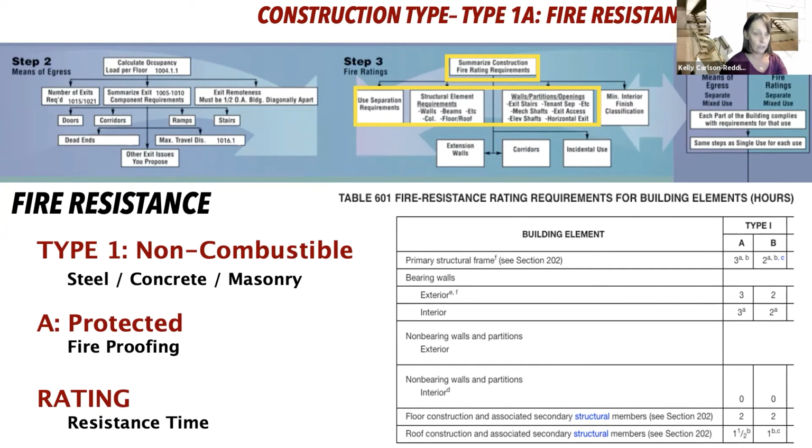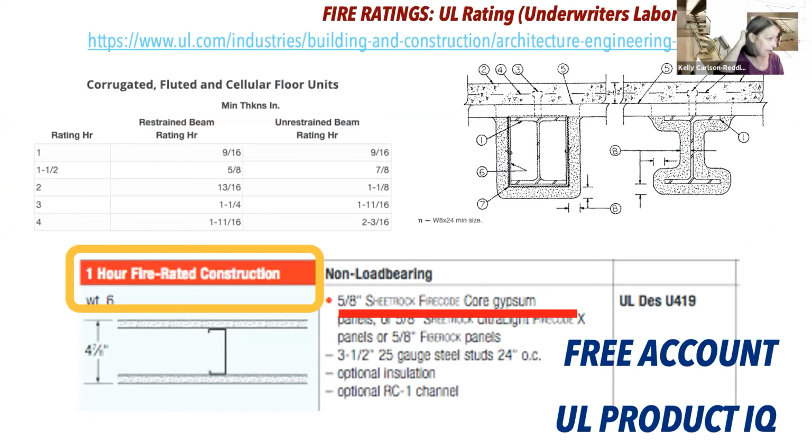But that's really more importantly what you're going to need to know now. We're not going to go in and do this right now, but I want to point you to what it would mean. And this is sort of what it really means. If you say, I have a 3-hour construction, then you go in and you say, okay, how do I achieve 3 hours of safety with a certain system? And so all of these construction systems are basically tested by either the manufacturers and verified by the Underwriters Laboratories. And this is just an example.